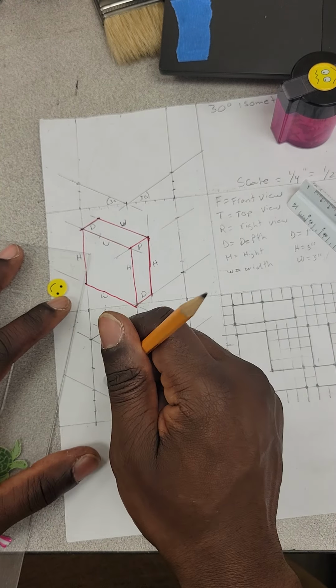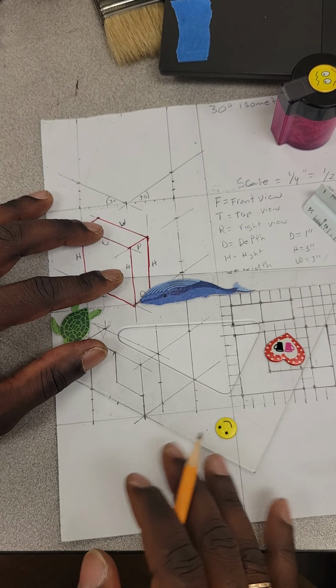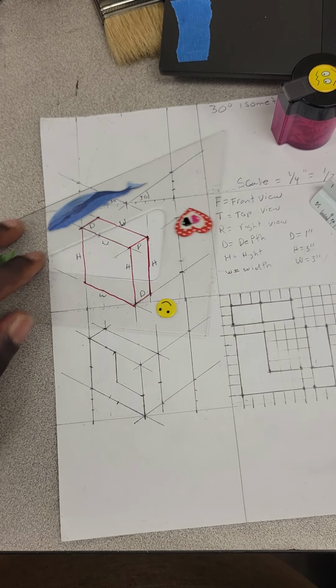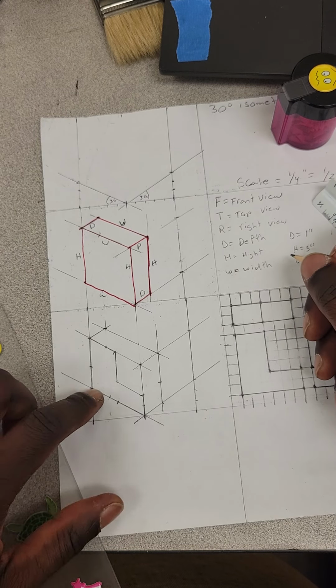Now you don't want to darken these lines too quickly, but just to see where you're standing right now, I'll do it for you. Don't darken these lines too quickly because you'll have to make some corrections on these lines. Just gonna give you a shadow of what you just did. So you just drew your first front view on a 30-degree angle. That's the view you're looking at. You don't want to make these lines heavy. Don't make these border lines heavy. I'm doing it to give you an idea of what you just did. So this is the front view.